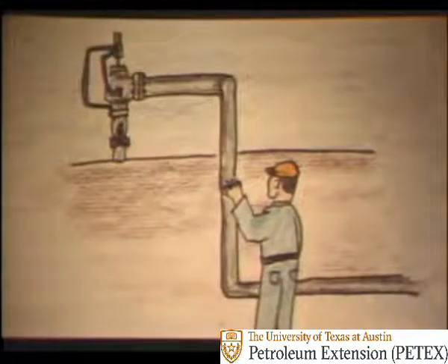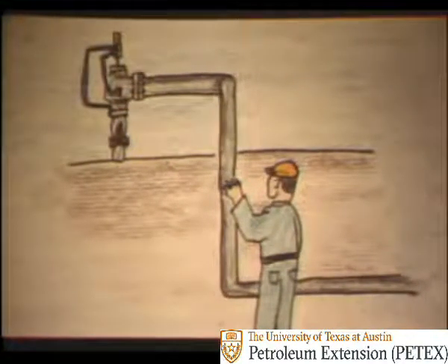A leaking safety relief valve sometimes is the cause for low pressure. A leaking safety relief valve can sometimes be detected by putting an ear to the flare line downstream of the valve and listening for a whistling sound, or by just feeling the line on both sides of the safety relief valve. If the line is several degrees cooler downstream of the valve, it's probably leaking. If you have a leaking safety relief valve, it will need to be checked by an automatic controls repairman.